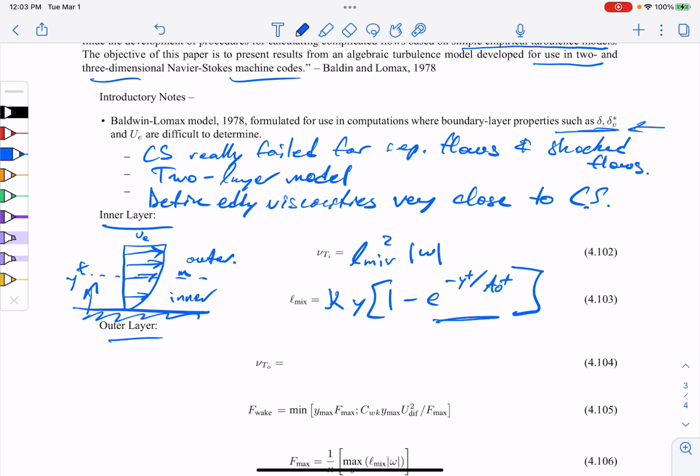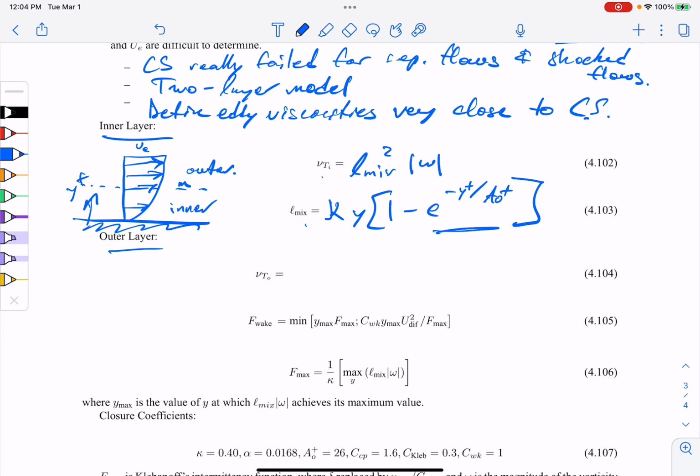So that's it. That's the inner model. If you already have your Navier-Stokes boundary layer code, you could just divide the flow into an inner part and an outer part, and define two eddy viscosities. Somewhere in the middle, they're going to meet at location M. You would just find that location where they cross over in your models, throw away the other part of the solution, and have one eddy viscosity, which you add into mu. We'll talk more about that when we introduce project 4.